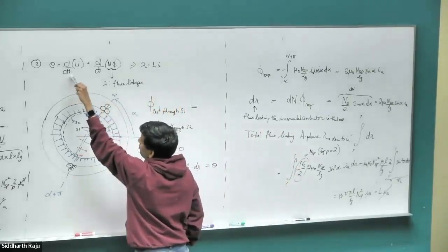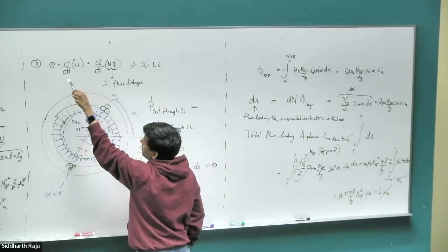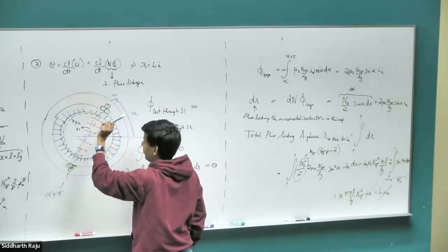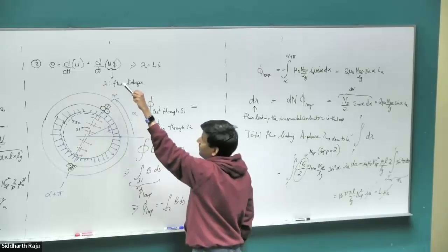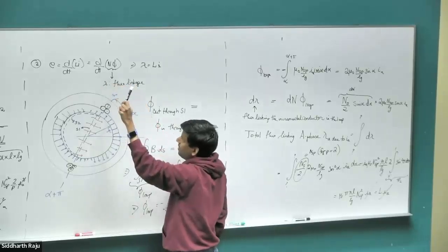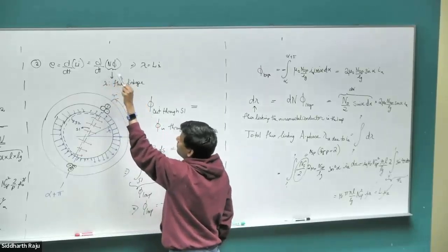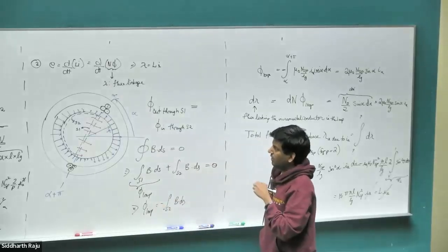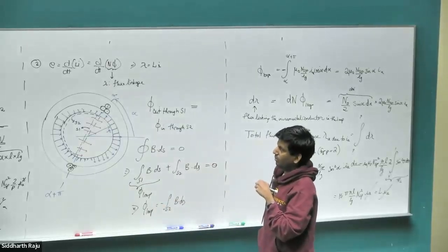Basically, using our previous expression, L dI by dt, we brought the L out when L wasn't changing, but that's no longer the case. When we go to the induction motor, L will change, so we're bringing that back in. And then N dφ/dt from our Faraday's law. Again, N is not changing, we can bring that in. So we have d(Nφ)/dt. So Nφ, which is flux linkage, is equal to Li.